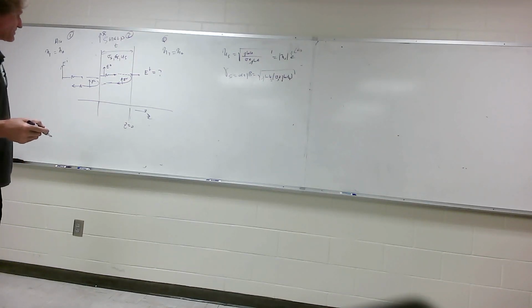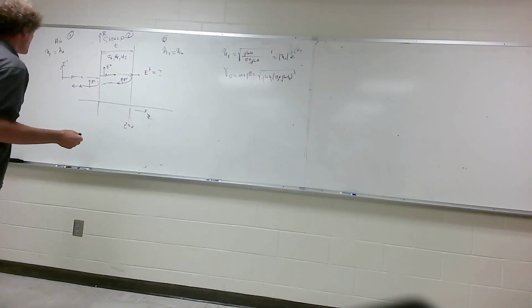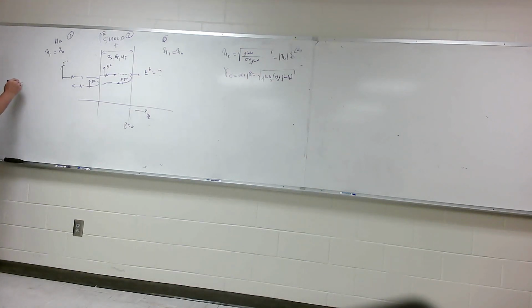Now we're going to have that. We know that over here, beta in region 1 is equal to beta in region 3, which is equal to omega over c. The reason we know that is because the frequency of a waveform never changes as it propagates in a linear material. Wavelength will change, power density will change, a lot of things will change, but frequency never changes. And you know, beta in a lossless region is just what?